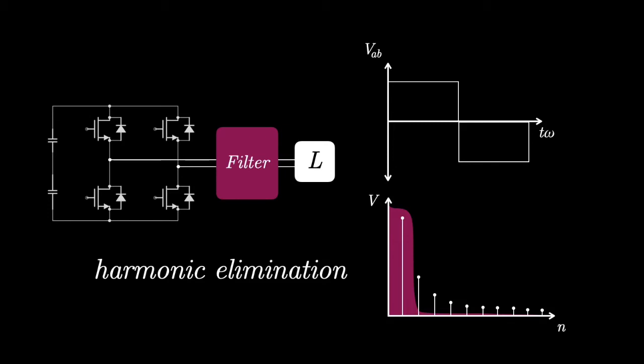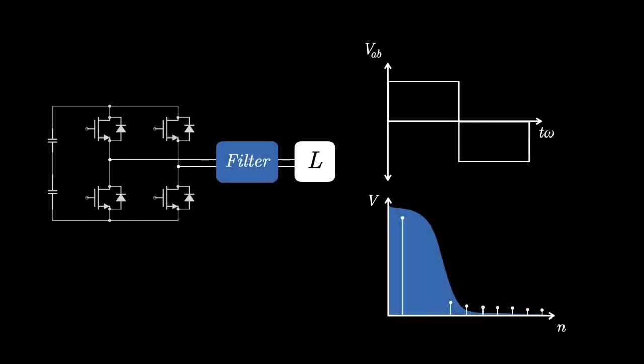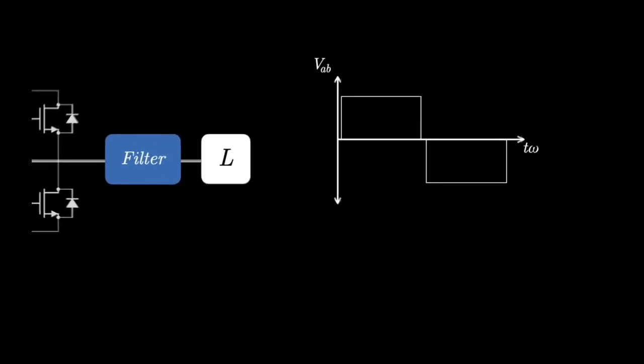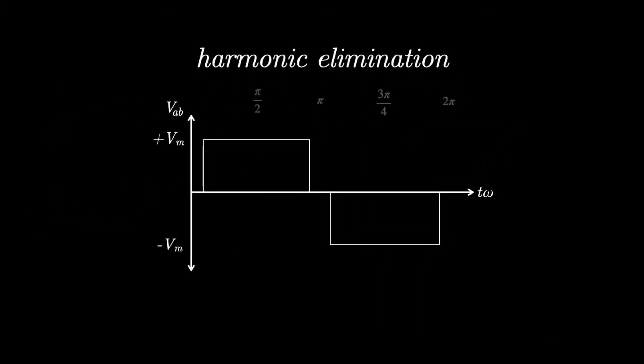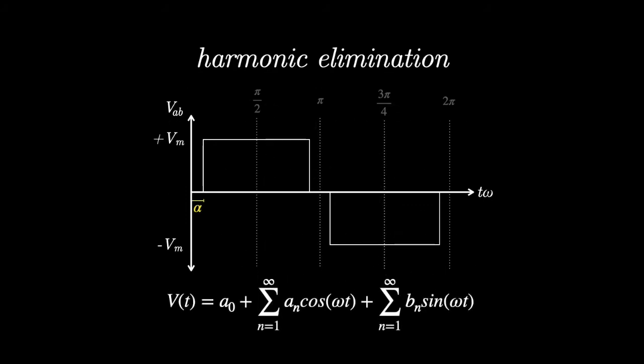We can eliminate certain harmonics in the circuit design using pulse width modulation. This will allow us to use a simple filter to cancel the remaining harmonics. For this, we will need to have an angle, and we will determine its size later on.